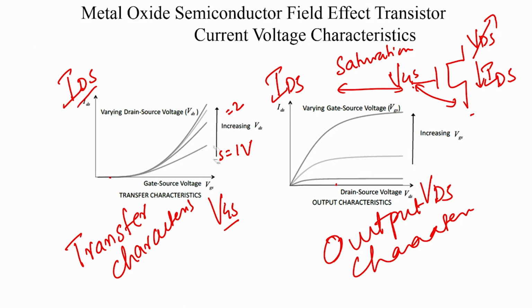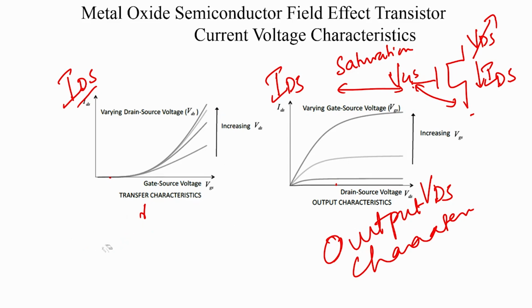Now, what do the transfer characteristics tell you? They tell you that till a certain point there is no increase in current. So, we could define a threshold voltage somewhere. If you take a very low VDS, if VDS is much smaller than any VGS that you are applying, then the characteristics is almost linear, like a straight line. If you project the straight line all the way back, you would intercept the x axis at the point of Vt, that will be the threshold voltage.